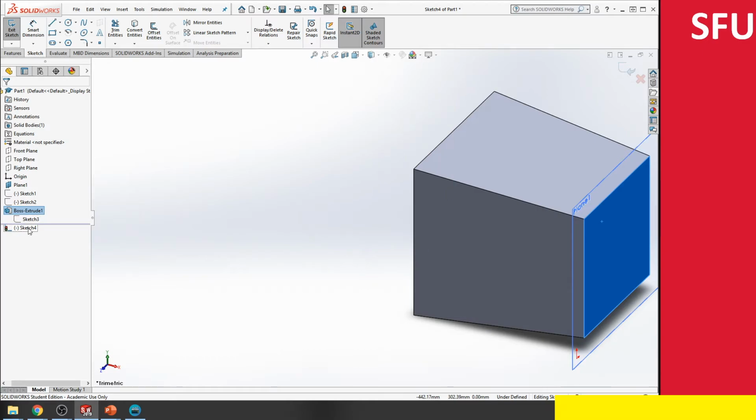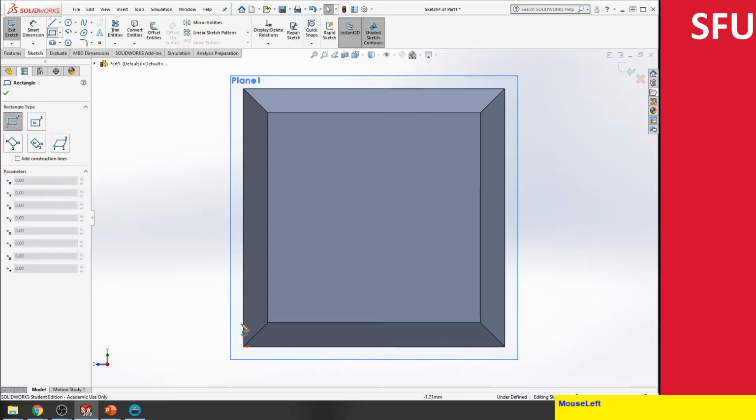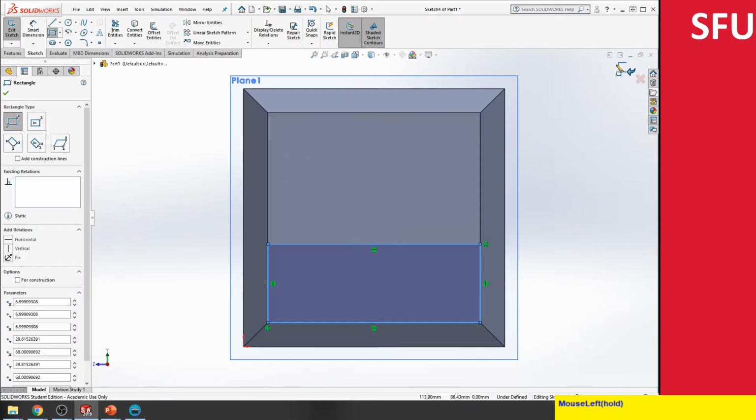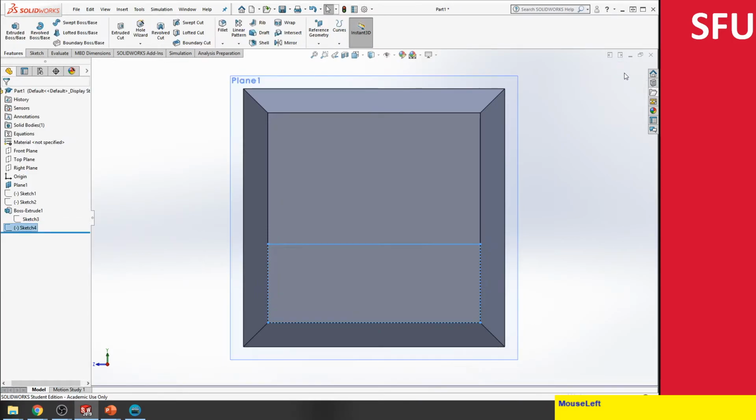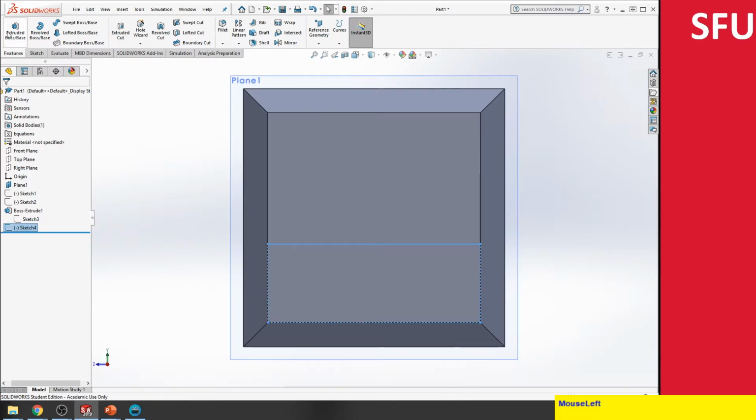Now again I'm going to go orient to view, and let's create a rectangle over here. As soon as I take it to this point, it constrains it there, and then I take it to this point, this gets constrained, and then we say okay. We right click here, we select the sketch and then say extrude.